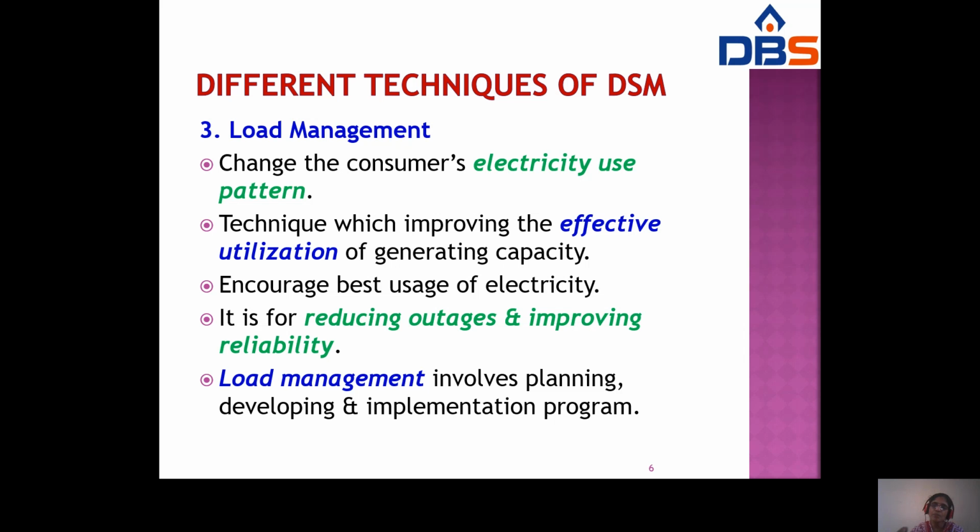Load management is a process of balancing the supply of electricity with the load by controlling the load. Generally, in real time, frequency sensitive relays triggering circuit breakers must be there. So load management is used to reduce demand for electricity during peak time, that is, load factor is equal to average load by maximum demand. Like that we have taken average load by maximum load.